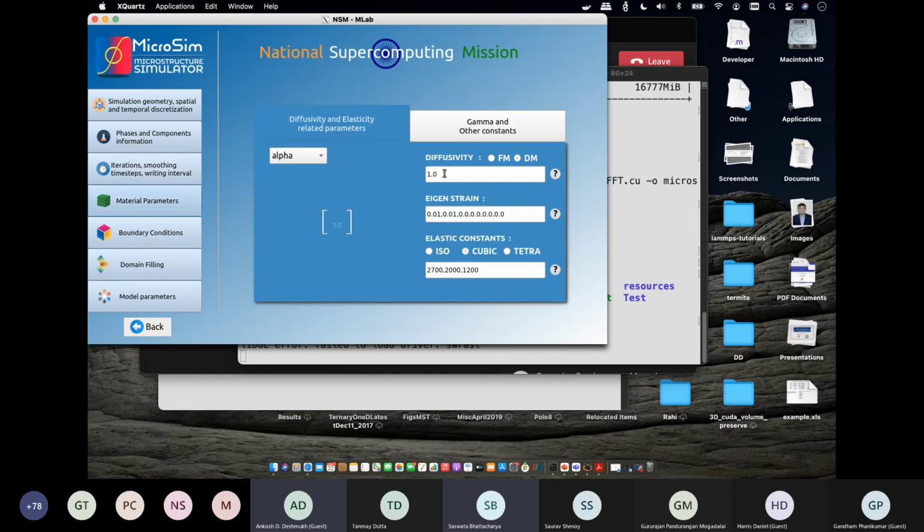So alpha phase, we are using diagonal diffusivities. However, again, you can use thermodynamic data and kinetic databases, all these things you can integrate and put. That is one thing that we are going to release very quickly. However, diffusivity, be very careful. Most of the diffusivity databases that come with the commercial software are wrong.